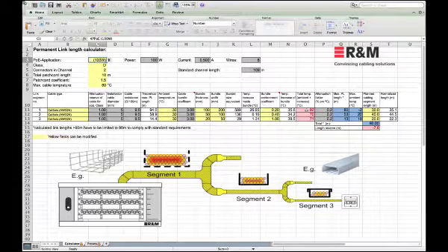With 92 degrees in segment 1, you will probably start to get real problems with destroying or melting the plastic material. On the other hand, we also see that the link reserve is too low. That means the attenuation is too high, and your 1 gigabit transmission would probably not work properly over the whole 90 meters. So all the links longer than 82 meters would probably have problems with transmission.